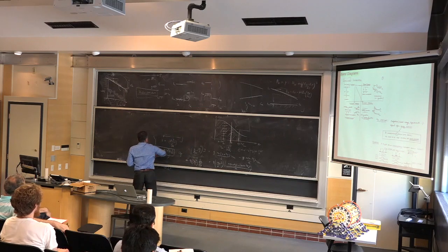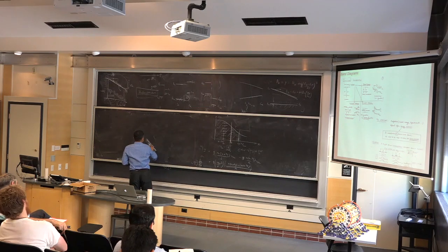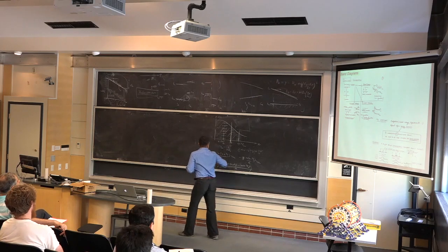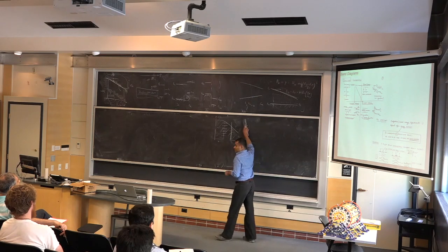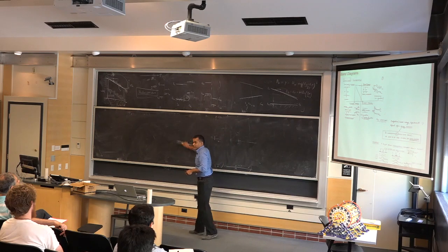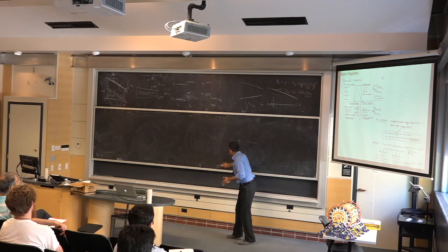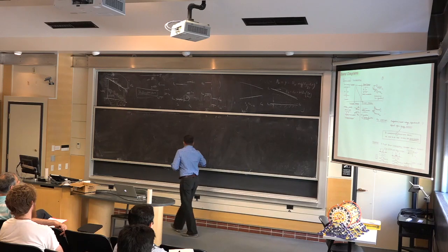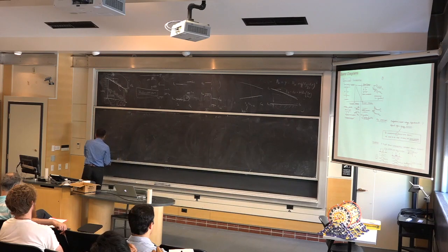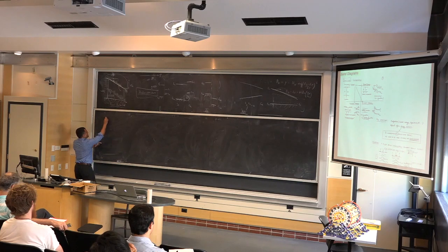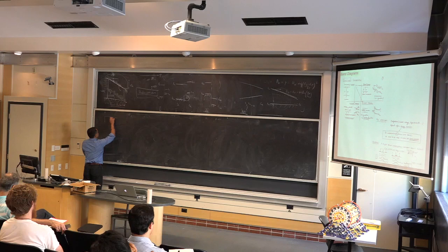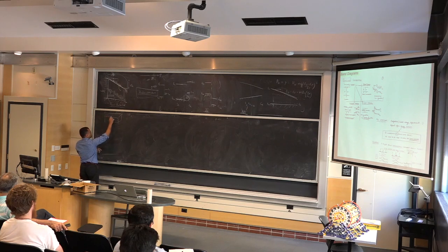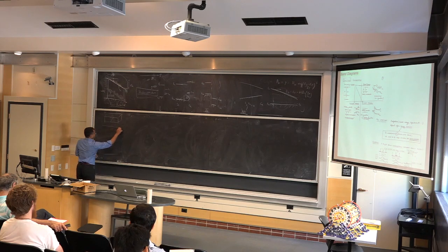And I think you can see that if I have a positive sheet charge, that charge is going to attract electrons. So that already tells you which way the band is going to bend, at least. That should be immediately clear. So what I'm saying is I take a block of silicon and insert a plane, by ion implantation or growth or whatever, a sheet of positive charges here. And I ask, draw me the energy band diagram in that direction.